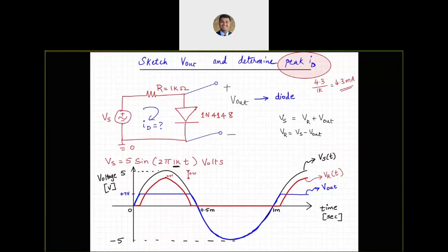So that is going to be the turn on voltage for the LEDs. And the green one probably requires like 2.3 volts to turn on. So it depends on the color of the LED as well. But that number of 0.7 is for the small signal diode 4148 and the Zener diode 1N751. Yes, it depends on the type.